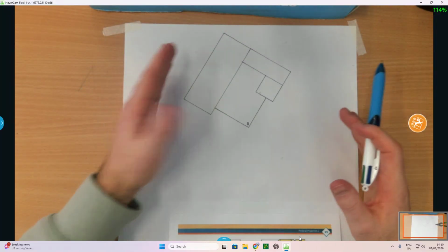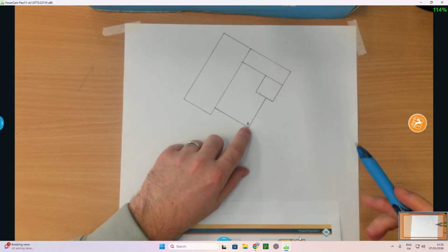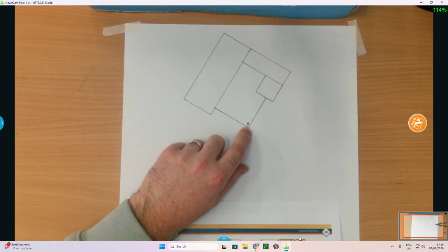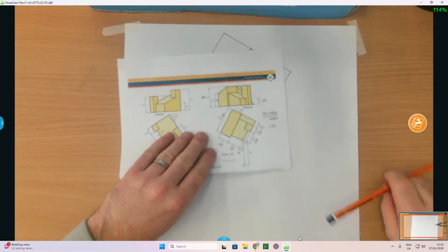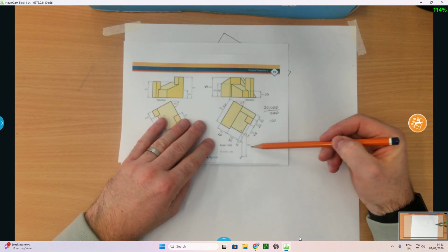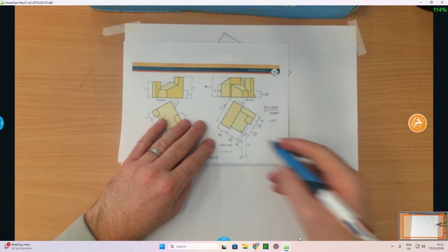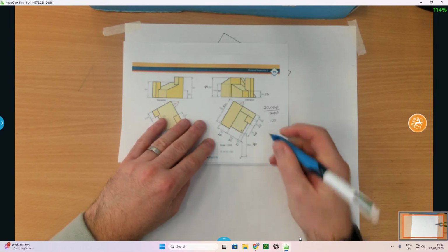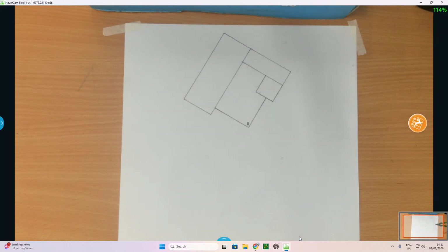Now, as always with perspective drawing, we draw the plan view first. I've done mine in portrait and I've positioned it up here. What they tell us is that the picture plane touches corner A. So the next thing is, from corner A, what is the distance to our spectator? It's a vertical line down at a distance of 18 meters. That will work out to be 90 millimeters away. So that's step number 1.